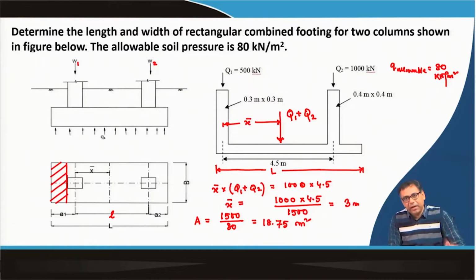So, that means settlement and bearing both are considered, and the minimum one is given as the allowable bearing pressure. Because last class I discussed that you can go separately and provide the minimum one, and there is a correlation also available, where you can directly get the allowable bearing pressure. But in the previous case we saw that the settlement consideration is giving the minimum value or the lowest value. That is why you provided that. So, here that value is directly given.